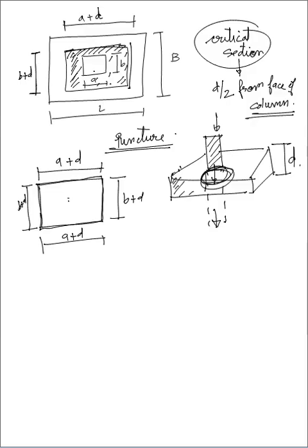When we find the punching shear, we have to check the shear force resisted by the cross-section area. So I will take this perimeter A plus d, B plus d, plus A plus d, plus B plus d. What will be my net punching force? That is P net.